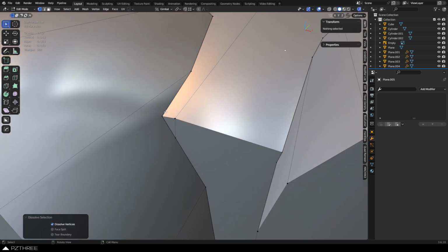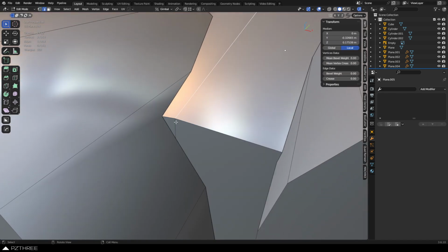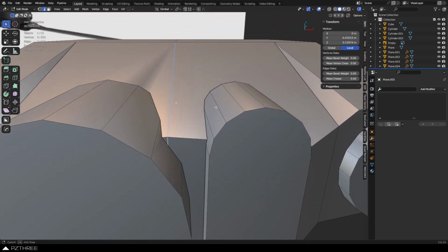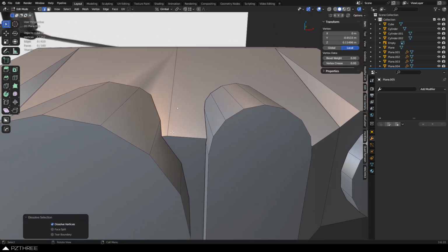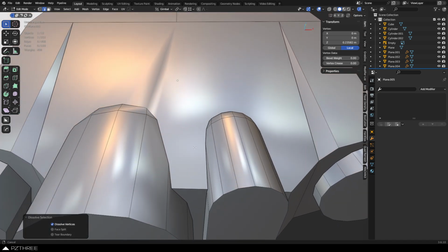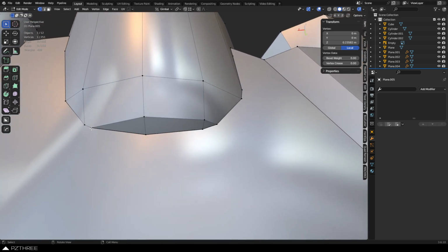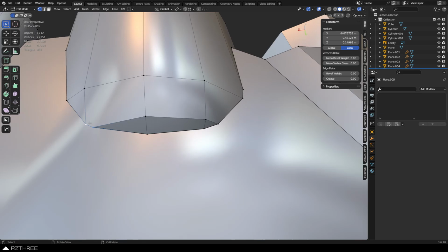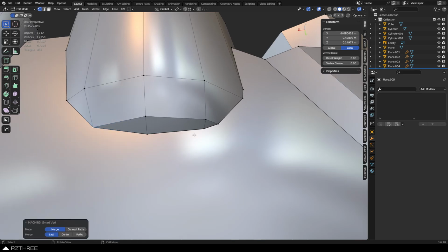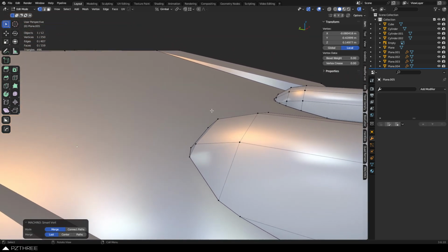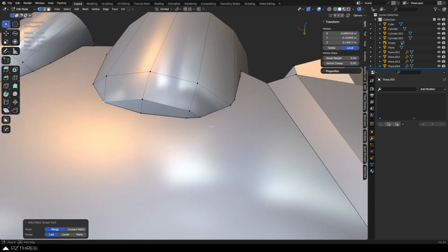You do want to get rid of excess. Whenever you do a Boolean, you don't always need all this stuff laying out and about. Maybe just get rid of that front one, maybe get rid of the whole thing down the middle, who knows. You just want to get rid of any kind of extras, and sometimes you might want to merge things together, maybe at center points, but usually you want to try to keep everything flat, so you'll try to go to one of the other vertices there and do something like that.